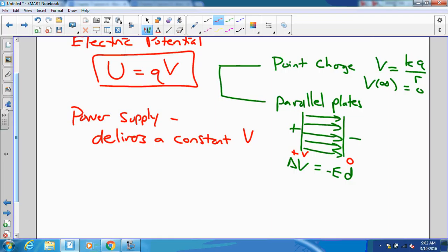What do you guys notice about the measurements on here? Anything? When he puts it down, what happens? It takes time to regulate. It fluctuates, and it takes time to settle down to its true value. And the reason for that has to do with the contact that's made here. Notice that I'm grounded, so I'm at 0 volts. Does that change? Yes, it does. But look, I'm conducting, but not perfectly.